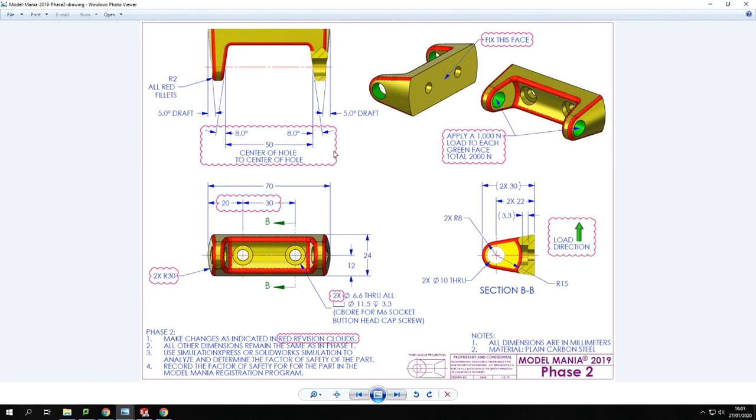I'm going to have to create an angle on the inside here. So I've now got an angle going through. Now I've got a 50mm offset as we did before, but it's set from the center of the two circles rather than the bottom. But I've got an angle there coming up of 8 degrees. So I'm going to have to put an 8-degree draft on that as well.